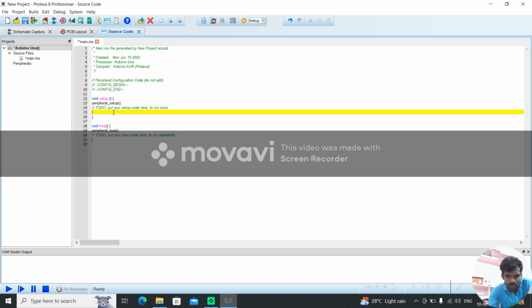So for that purpose, I would like to write pinMode of LED, comma, it is OUTPUT type. So we should define that LED.